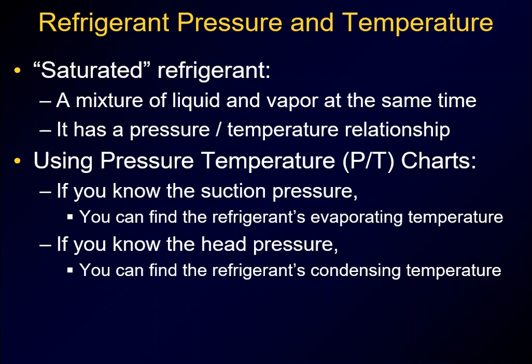And so your low side temperature is going to have a saturation point where the refrigerant in those lines changes from a liquid vapor mix to 100% vapor. It's the evaporator, so you think about it as evaporating. The refrigerant inside of that coil is constantly in the process of evaporating, and when it completely becomes 100% vapor, that's a saturation point, right? So that goes from latent to sensible.